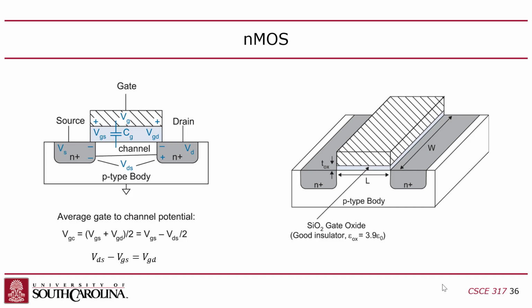So either I'm sending current to my outputs through my PMOSs, or I'm sinking current back through my NMOSs, right? So either I'm pulling up, which means I'm charging up my load capacitors, or I'm discharging my load capacitors. The more current, and this only happens during a transition. Once it's discharged, then nothing. This is the dynamic power consumption part. Basically, the idea is that I'm charging up these gates, or I'm discharging them. I need a lot of current to do that faster.